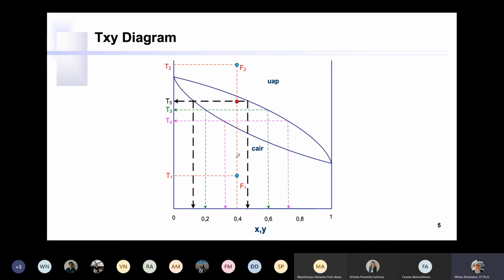Okay. Conversely, you also can check if you heat it up more. Here, of course, you also can do things like I did before. So for this case, the XA would be maybe less than 0.2, maybe 0.11, and YA maybe from this area. This is 0.5, maybe about 0.47. What I'm doing is only approximation, but for you, please do it using a ruler. Okay, and you also can find the ratio of liquid to vapor.